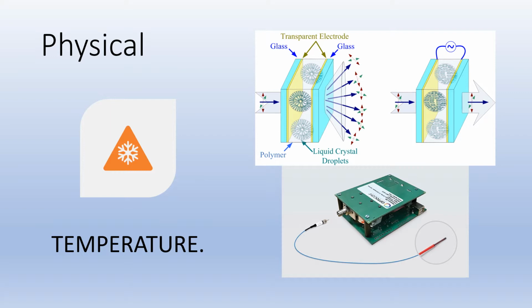They are important because they have a variation of light at different temperatures when a specific wavelength is disturbing it. An interesting application of liquid crystal thermometry was in a catheter for blood flow measurement by the thermodilution technique.